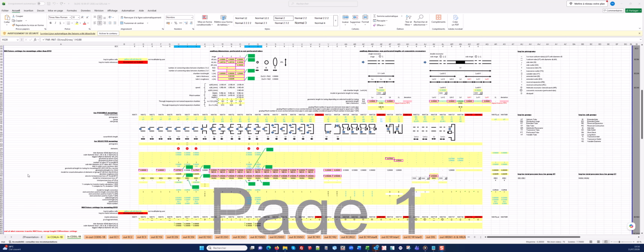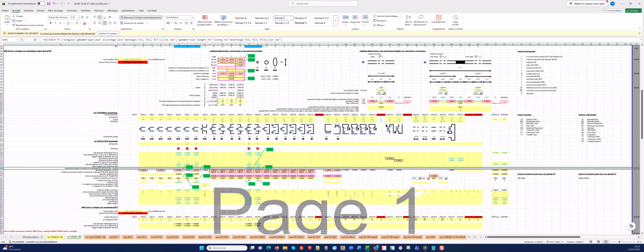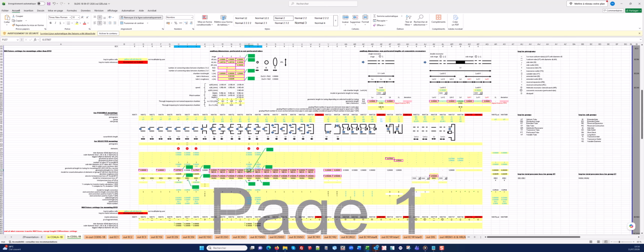For this, the software is displaying the dimension, allowing a tuning of the chamber to optimize the performance. This value we should report here for the extended inlet, for the extended outlet, and also for the inlet uniform tube and for the outlet uniform tube. The length of the central tube being computed accordingly.